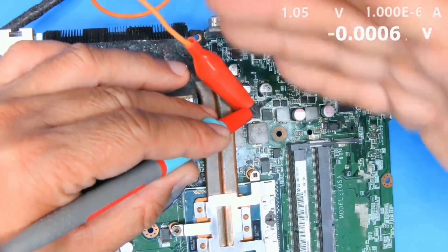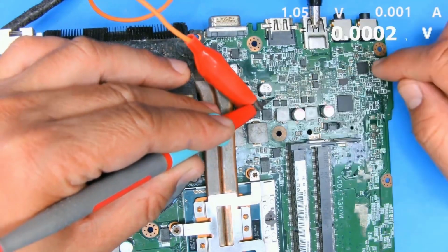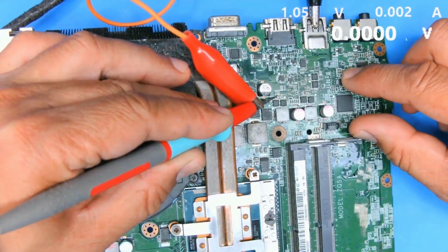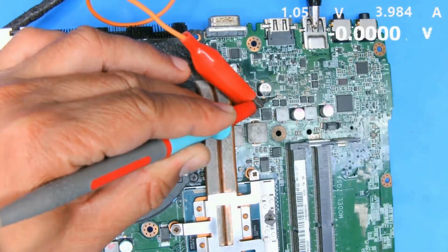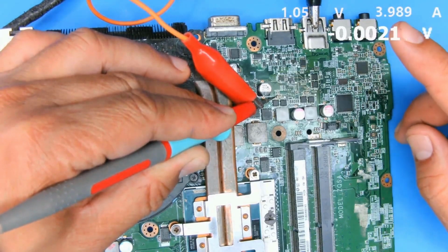To inject power, we need to find the positive side. Where is the positive side? We have to use the power supply to find it, just like earlier. We know the positive side is on the left, so we inject power there. Now we should be able to find the shorted component. The one that is shorted will heat up.